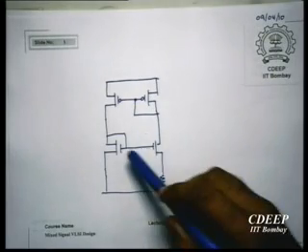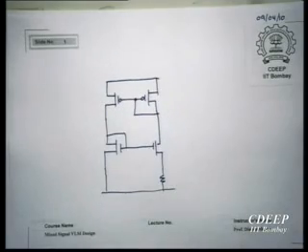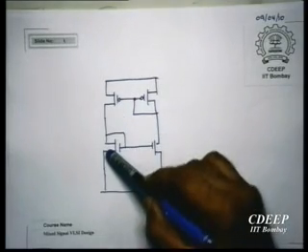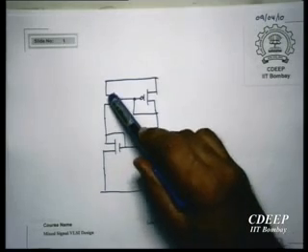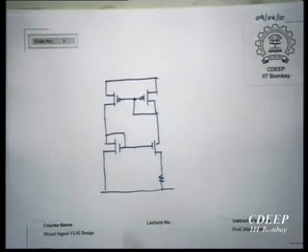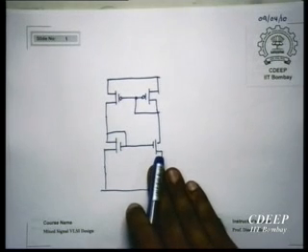Now let's say that the current through this is I. Then the current I flows here, and that induces the current I here, and because this is a current mirror, this is also I, therefore the right-hand side is also happy. So that means this system is stable. But wait a minute, there is a problem. That means this system is stable at any current. Yeah, why not? Right now we are talking as if R is not there.